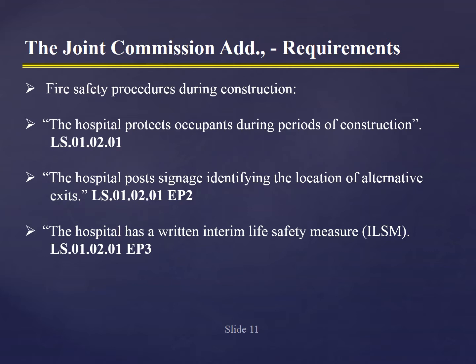In fact, language in recent days or years has to do with people doing an interim life safety measure immediately upon identifying a problem, and immediately has been identified as the same day plus one shift. And if you don't do that, you have to do an ILSM. This has absolutely pushed the need for ILSMs to be understood by everybody in facilities management, not just the supervisor, manager, and the director, to maintain compliance.